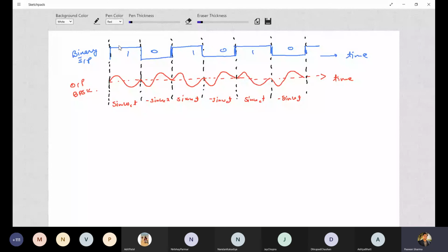If 1 had been here, the same sine omega ct you will have to draw like this. If you have any query, any doubt, please share, or else we are good to finish this lecture today. I think sufficient has been covered. Now you should feel confident with the understanding of phase shift keying, specifically binary phase shift keying, where we get reverse phases for bit logic 0 and 1. How do we do that? We make use of a circuit we call a balanced ring modulator. We have also seen the inside of that balanced ring modulator circuit, how it is capable of producing reversed phases with reference to the applied bit input data polarity, and we get output phases. We have also represented them in time domain, in phase domain, and in constellation space domain.